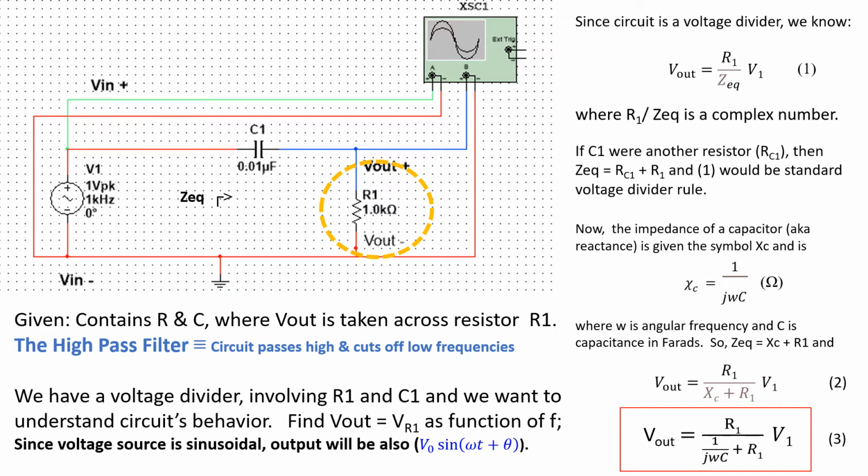High-pass means that when the circuit is sent a series of voltages whose amplitudes are changing, the voltages with higher frequencies appear across the resistor, and voltages with lower frequencies are suppressed. That is, higher frequencies are said to pass, and low frequencies are blocked. This is the essence of the term filter. Only desired components are allowed to appear or pass through the circuit.